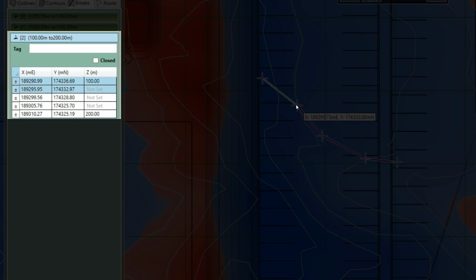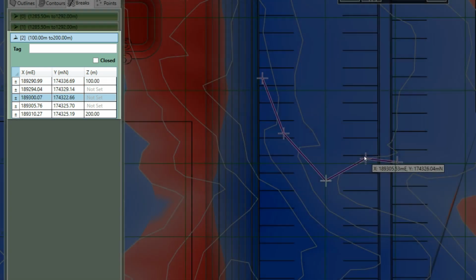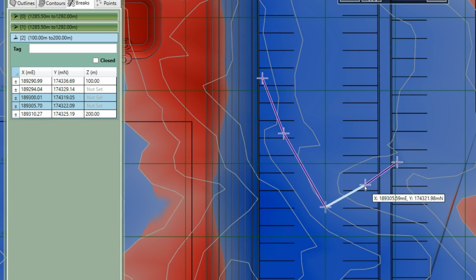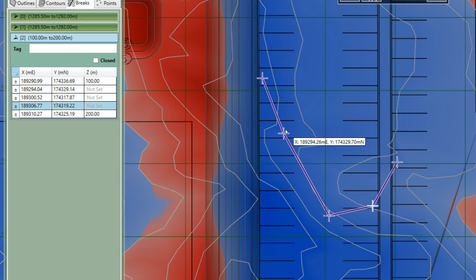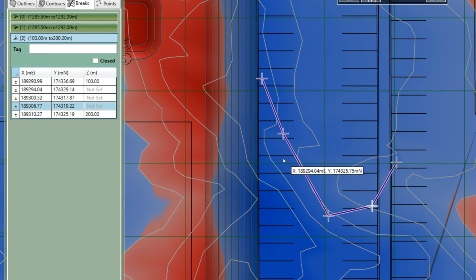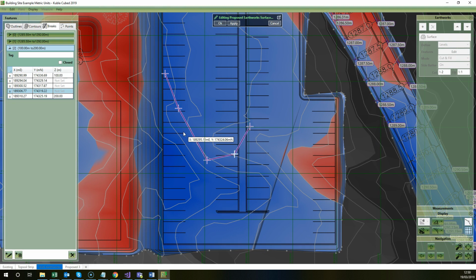Now if you want to edit these, you can move them around and the Z value stays not set, so it gives you quite a lot of power to have the points where you've set a value, and then you can still change the ones where the value's not set, and the interpolation is done at calculation time, so you don't have that same problem as before. It's quite an important improvement, that, and people who've been using break lines will sort of know the value of that.